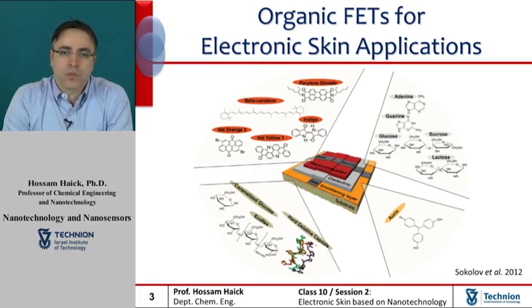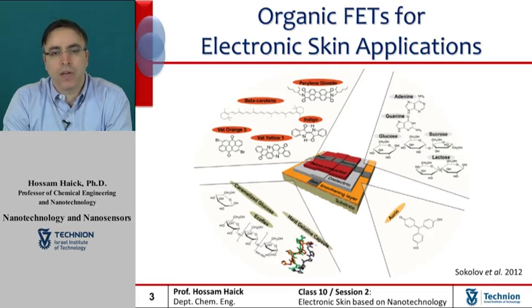First steps towards biodegradable electronic skin have been achieved with field effect transistors based on polyvinyl alcohol as gate dielectric, bithiophene derivatives as organic semiconductor, and polyglycolide derivative as degradable substrate. A list of materials that have a high potential in bioelectronics or bio-inspired devices based on organic field effect transistors is presented on the screen.